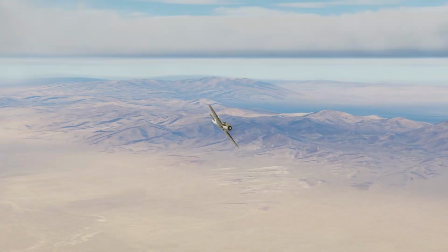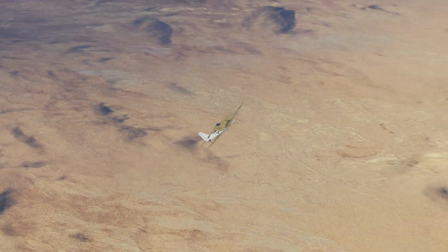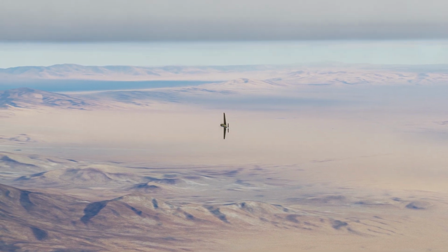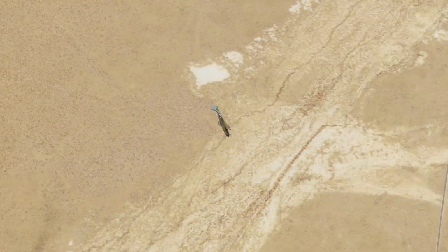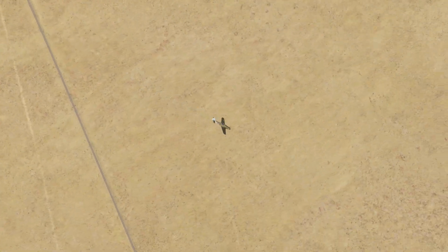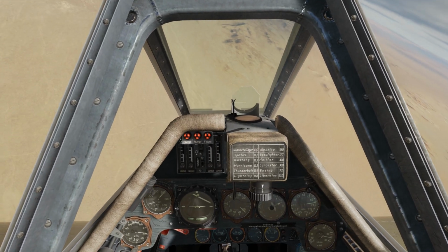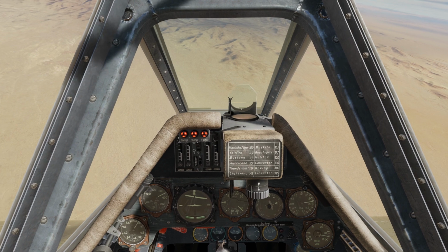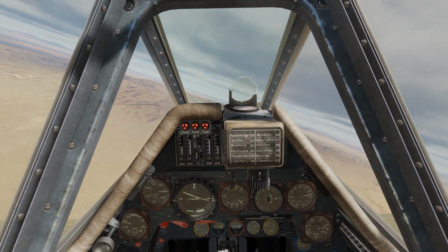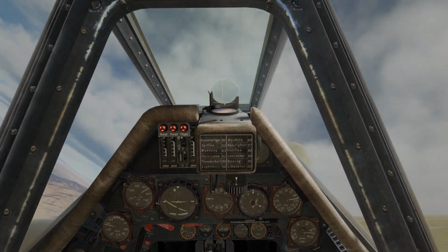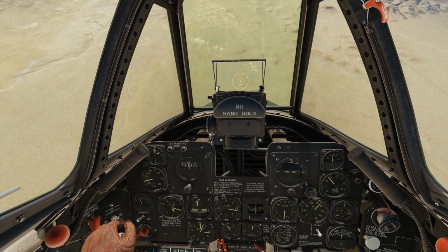For this reason, the air over the top of the wing will follow a slightly different path. This will change how the plane reacts to changes in angle of attack. When pulling high loads at high speeds, the wing will stall violently at speeds that it should not. This is called a high-speed stall. To sum it all up, the incoming flow of air will behave like it has a lower speed. That's why this is called equivalent airspeed.